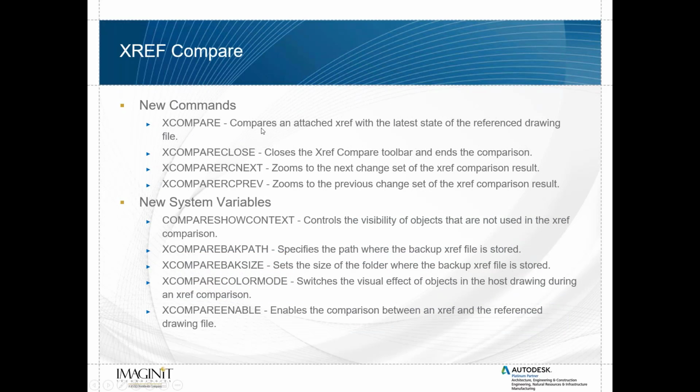Right, new commands: XCompare compares an attached XREF with the latest state of the reference drawing file. XCompare close closes it. XCompare next zooms to the next change set of the XREF comparison result. XCompare previous goes to the previous.